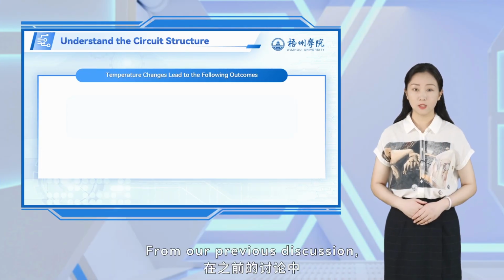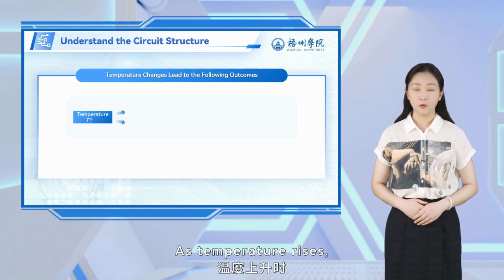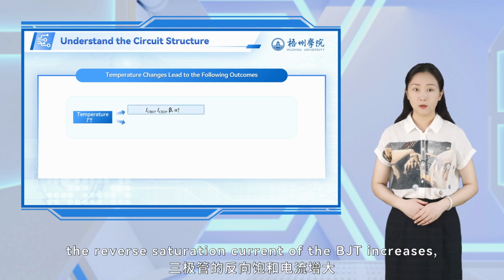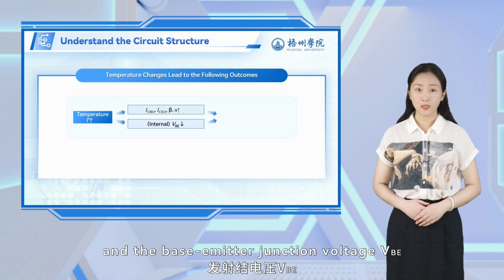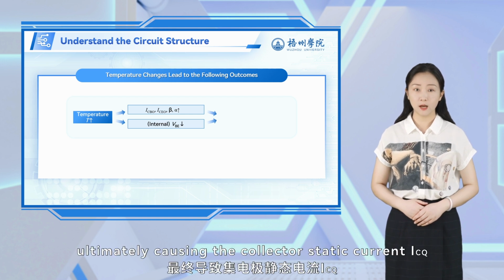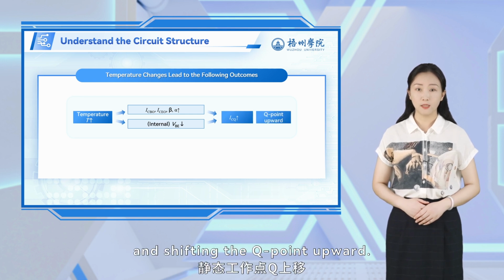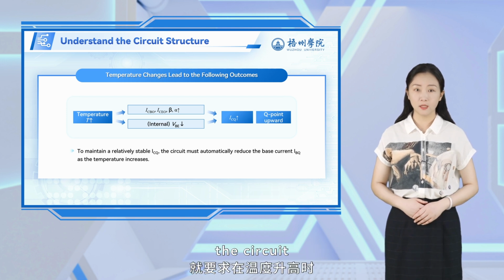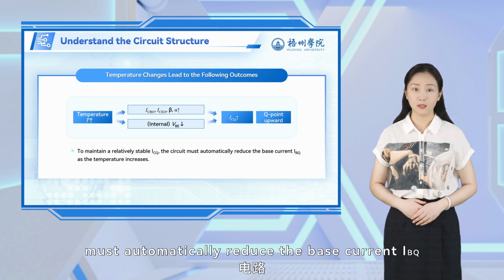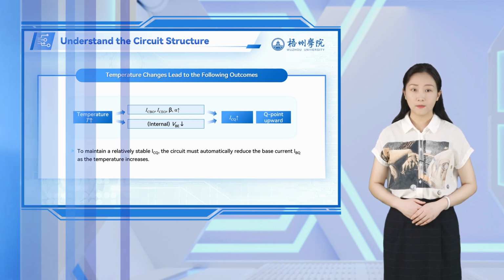From our previous discussion, temperature changes lead to the following outcomes. As temperature rises, the reverse saturation current of the bipolar junction transistor increases, the current gain beta increases, and the base emitter junction voltage VBE decreases, ultimately causing the collector's static current ICQ to increase with temperature and shifting the Q point upward. To maintain a relatively stable ICQ, the circuit must automatically reduce the base current IBQ as the temperature increases. How can the circuit achieve this?